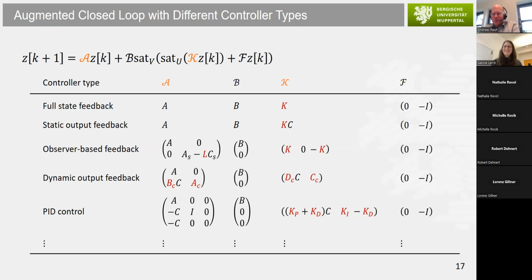Okay, you want to deal with a nonlinear system, for example, stabilizing an inverted pendulum. And the typical control strategy for an inverted pendulum would be, first of all, to perform a swing up, maybe energy-based swing up, and then in the vicinity of the unstable equilibrium of the upright position, you switch to a linear control strategy. And I think definitely what is doable with your approach is that rate and also magnitude restrictions of the linear controller can be taken into account in the vicinity of the upright position.